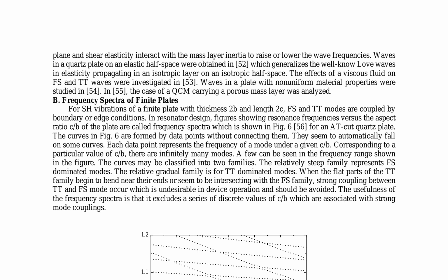This is particularly relevant for understanding the behavior of face shear, FS, and thickness twist, TT, waves, as well as waves in plates with non-uniform material properties. The case of a quartz crystal microbalance, QCM, carrying a porous mass layer has also been extensively analyzed.